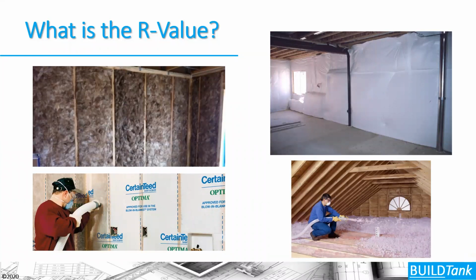In the 2021 IECC, this becomes a little bit more straightforward. There is a specific requirement now in the 2021 that the installer leave a certificate after installation certifying the R value of the material that they've installed when it is not specifically labeled by the manufacturer there.